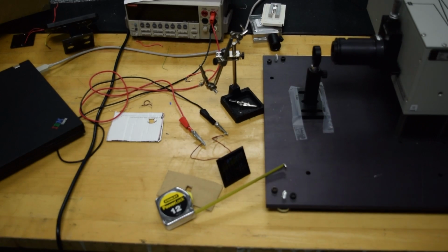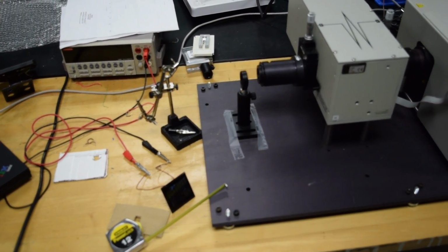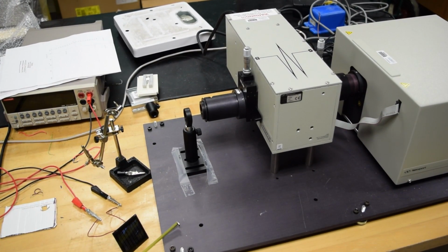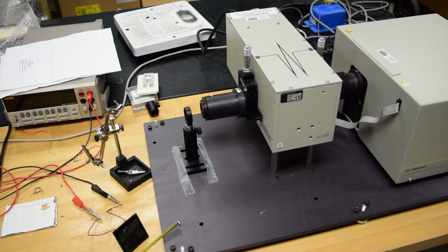The reason we're doing this is because our Keithley meter is actually not sensitive enough to be reading the low voltages or the low currents coming out of this encapsulated solar panel. So what we're doing is we're increasing the resistance, measuring the voltage, and then using V equals IR, we can solve for the current by solving V over R. So in this experiment, we'll be measuring the resistance and the voltage being produced by the panel.